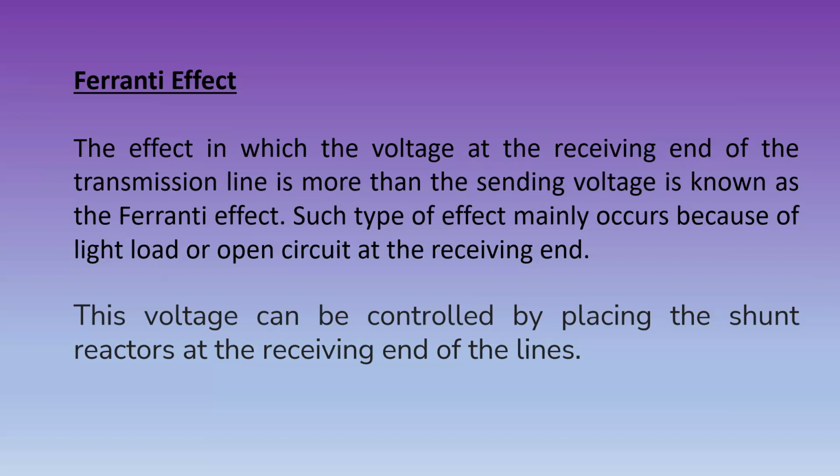This is the problem we get in the transmission line, mainly in three-phase lines, because the three phases are not spaced equilaterally. That is the reason for transposing the transmission line. So what are they going to do? They will exchange the position of the conductors at regular intervals of time. We have to check the line, exchange the position, and see whether it is spaced properly, equilaterally, so that the circuit will be balanced, uneven current can be avoided, and we can get a good transmission.